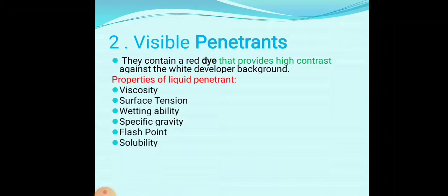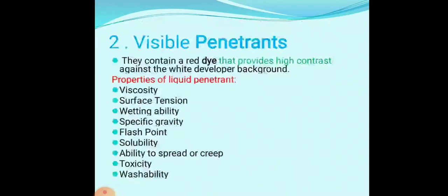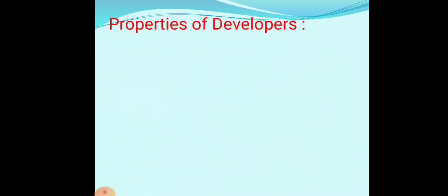And then solubility, ability to spread or creep, toxicity, and washability. These are some properties that should be considered while selecting the penetrant.